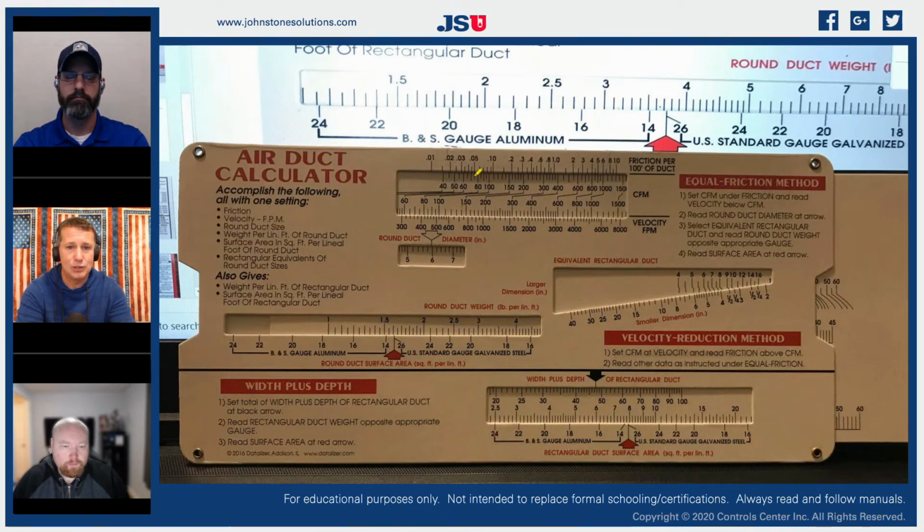0.05 on a 6-inch round is now good for 75 CFM. So if I'm designing the ductwork for this entire structure, and my engineers told me that I can only have a 0.05 on my supply, I have now gone from 100 to 110 CFM all the way down to 75 CFM on that same 6-inch line. So we have to set our ductwork properly. We have to set it for the static that is on our system.